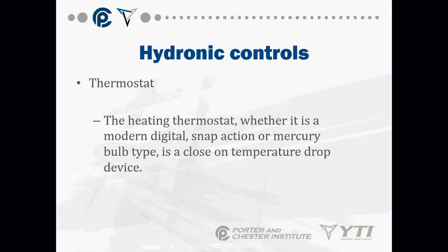What device is on the boiler that's going to send the signal to the rest of the operation to tell that burner to come on and off? What is that device called? The Aquastat. So we just add another component to the list of things that's going on.